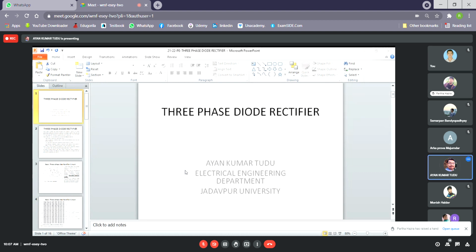Okay, so what I was saying: the single phase AC to DC converters are injecting low frequency harmonic current in the input AC line. So these are very difficult to filter in the input AC line, and the situation becomes even worse when we have capacitive loads, that is, more harmonic currents would be introduced into the system. Many of these disadvantages are mitigated by using our three-phase AC to DC converters.